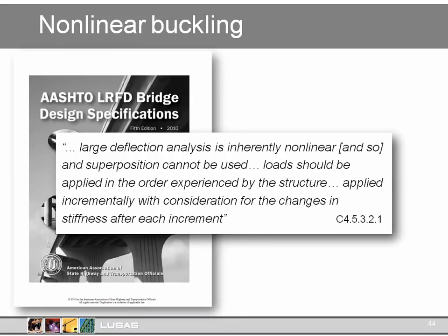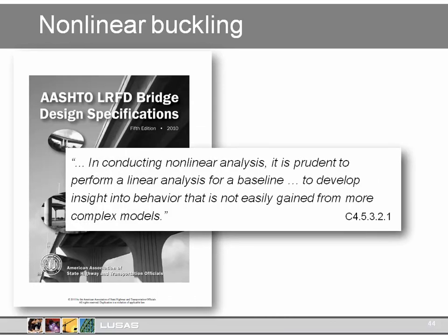AASHTO describes this well and points out the important implication. Large deflection analysis is inherently nonlinear and superposition cannot be used. Load should be applied in the order experienced by the structure, applied incrementally with consideration for the changes in stiffness after each increment. It also provides very helpful advice. In conducting nonlinear analysis, it is prudent to perform a linear analysis for a baseline to develop insight into behaviour that is not easily gained from more complex models.